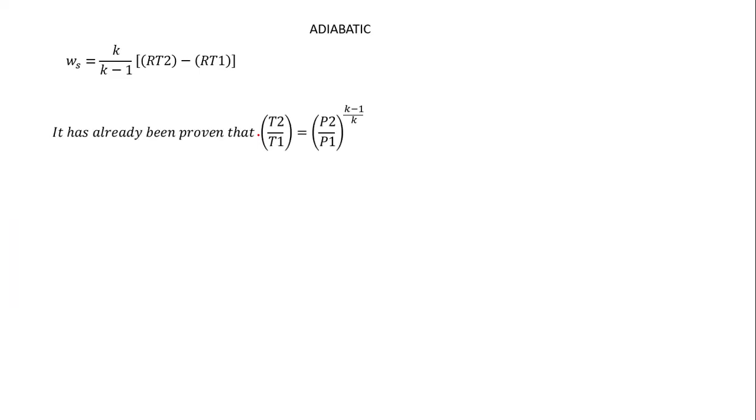So I can factorize R out, right? But even before we do that, from what we saw when we were looking at the isentropic relationships, we had a relation for T2 and P2. The reason why we're doing this is because we are dealing with the work. We want to see what happens as we are changing the pressure because we are dealing with a turbine. So we know that there's going to be some kind of pressure difference, which we can easily measure. So we want to work with pressure as well. So I can replace T2.